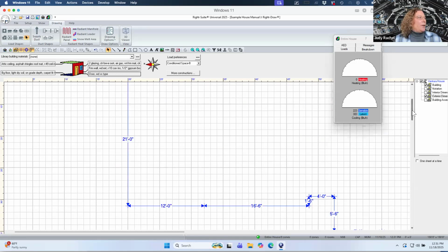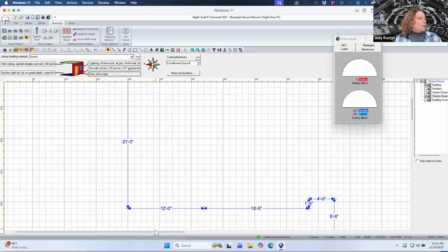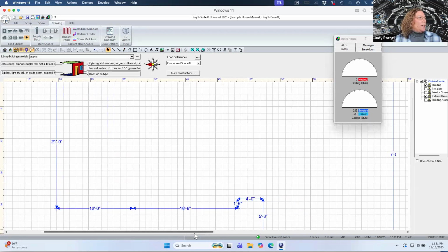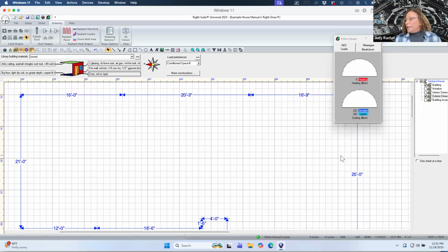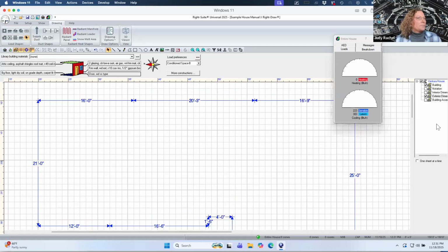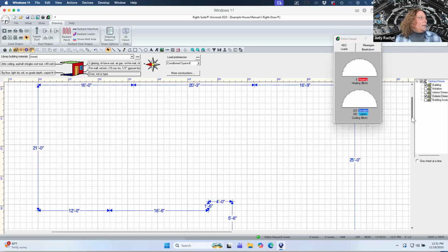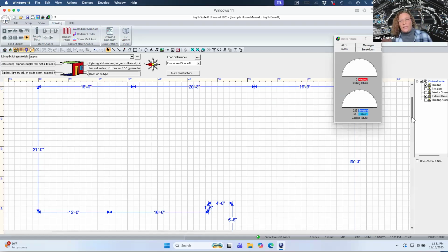So when I go out to a house, an existing home, I typically will measure it and just put the dimensions on the screen like this, like I've done here for you all to see. And then because the Manual J procedures are to measure the exterior walls, not the interior. And that's a problem with a couple of those softwares that are actually powered by Manual J, Amply and Conduit Tech in particular, which actually use the scanning softwares.